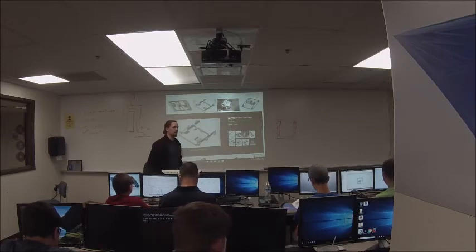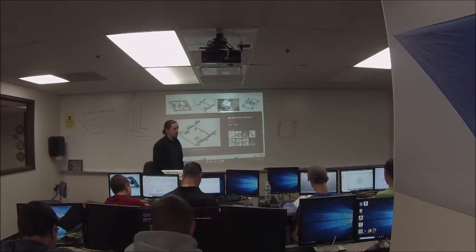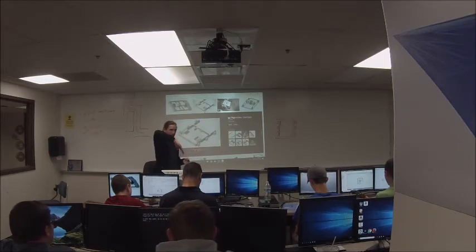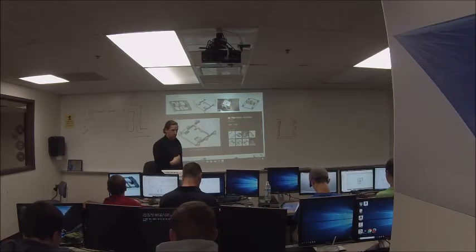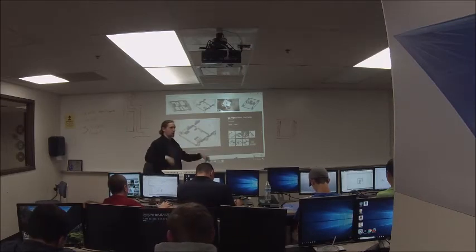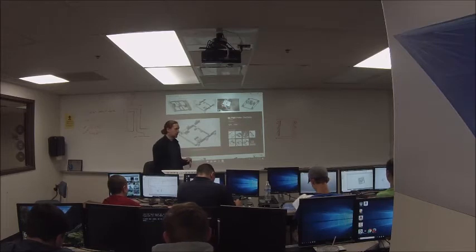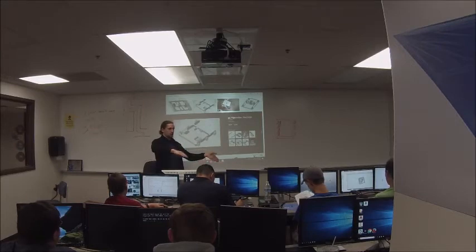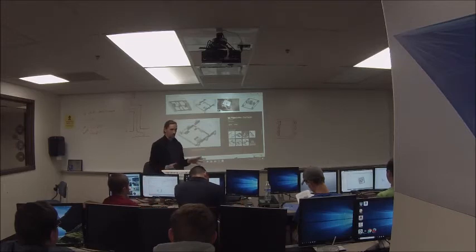Okay, and our last drivetrain here is technically semi-holonomic, which is not a well-defined term. Swerve drive is not actually what's called a true holonomic drivetrain, and I'll explain that in a minute. Swerve drive typically has 4 independently rotating modules, so it has a wheel that can rotate on a swivel 360 degrees, and that wheel is driven. And it's got 4 of those. Each corner of the robot has a wheel that can turn independently and drive independently. What that allows you to do, using some creative programming, is point them in different directions, drive all of them at the same time, and you get really smooth holonomic motion, or semi-holonomic.